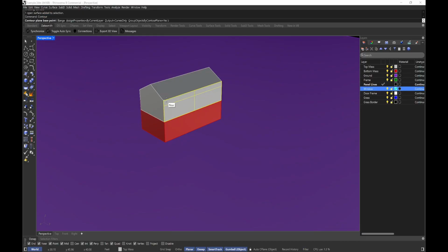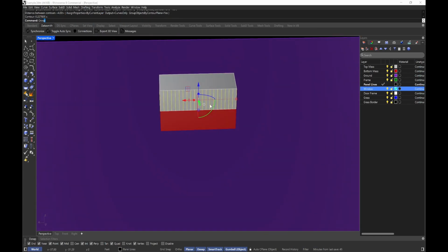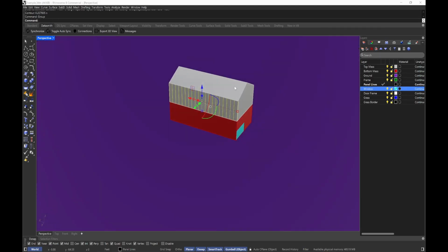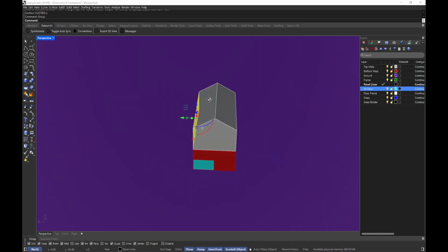And I'm gonna select this and I'm gonna go just from here to here. And yeah, I'll do this as 4 feet, is good like that. And let me just go ahead and group it. I have it active on the layer that I want it to contour. Okay, so that's important. You always want it to be active in the layer that you want to contour because it just saves you time switching layers.